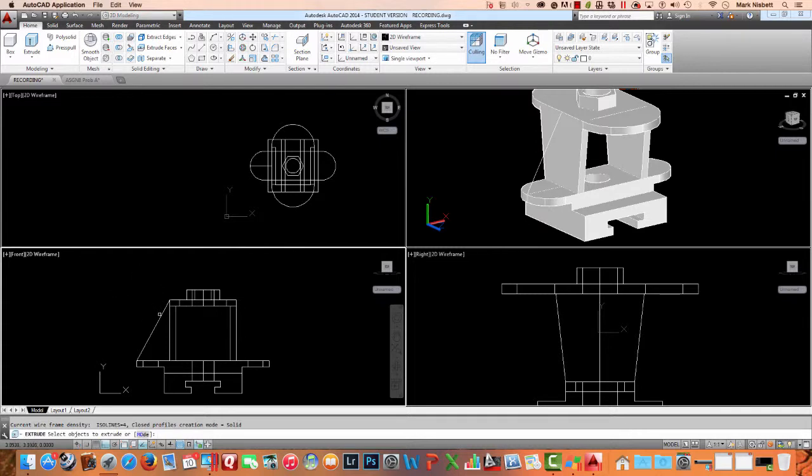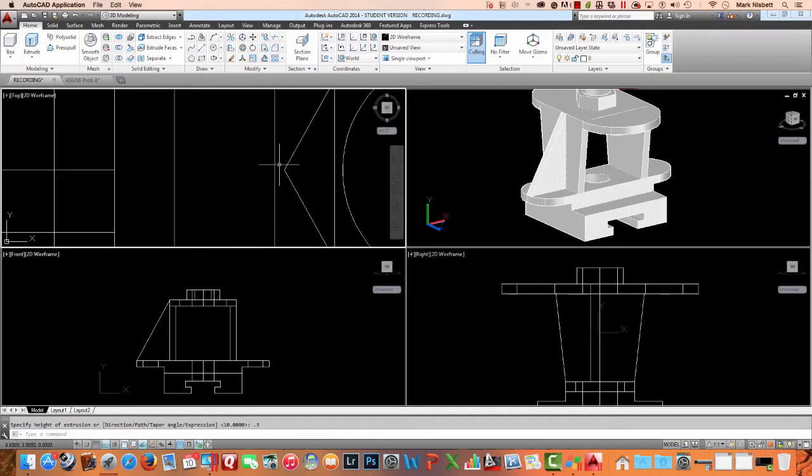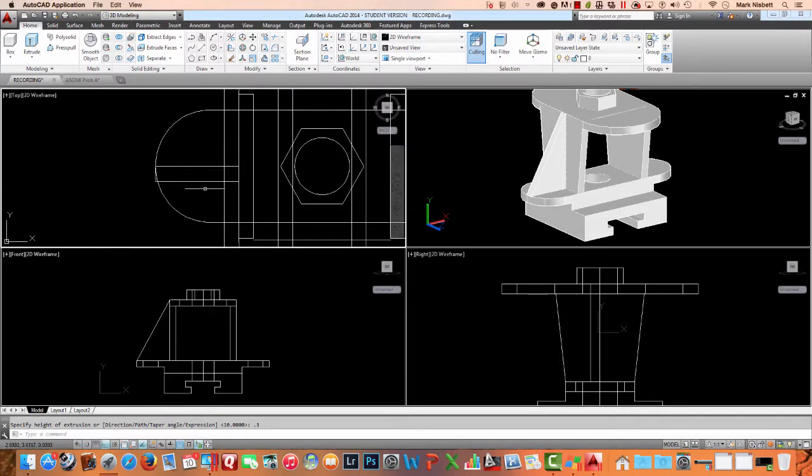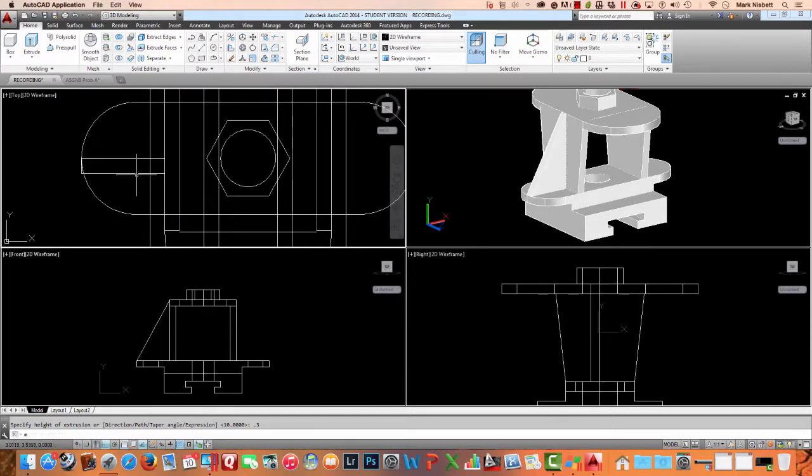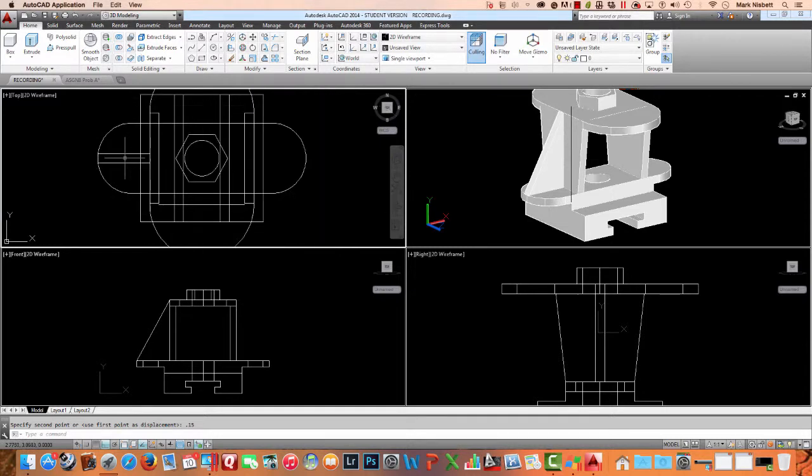We'll do an extrude on this, and we're going to extrude it 0.3, so you can see here how it's moved to this front. So I'm going to use the move tool, and I'm going to just push it back 0.15. Okay, so that should be dead centered now. Don't worry about this little part down here. That's how it's supposed to look.